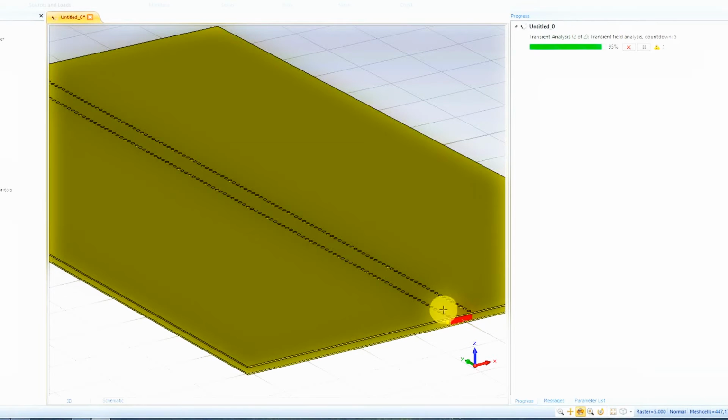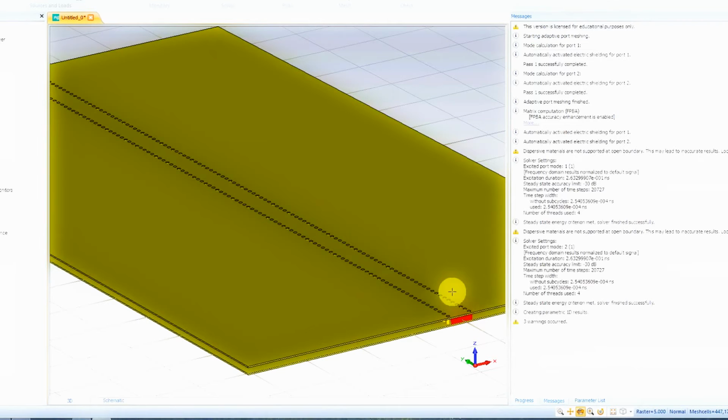And if you want to obviously verify the response of your waveguide structures over the cutoff region, you should use the frequency domain solver. But if you're doing parametric sweeps or optimizations, then I would suggest that you limit your frequency range to the modes that pass, and do that. And then once you've optimized your design, then it'll be done.